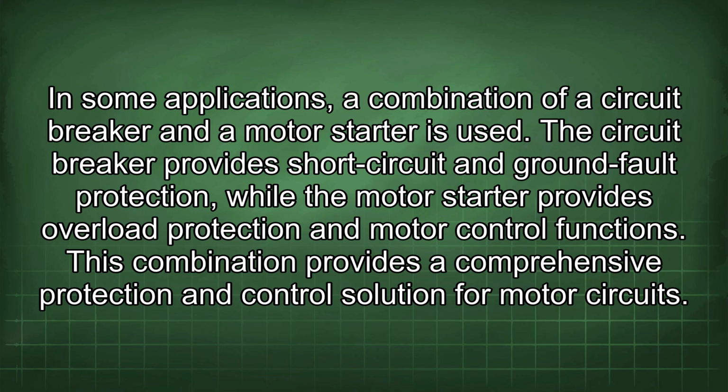In some applications, a combination of a circuit breaker and a motor starter is used. The circuit breaker provides short circuit and ground fault protection, while the motor starter provides overload protection and motor control functions. This combination provides a comprehensive protection and control solution for motor circuits.